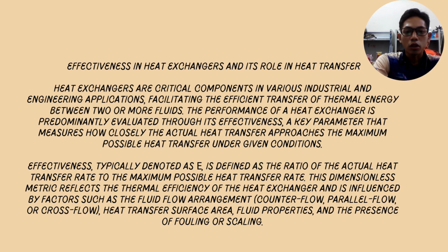Effectiveness, typically denoted as E, is defined as the ratio of actual heat transfer rate to the maximum possible heat transfer rate. This dimensionless metric reflects the thermal efficiency of a heat exchanger and is influenced by factors such as the fluid flow arrangement, counterflow, parallel flow or cross flow, heat transfer surface area, fluid properties, and the presence of fouling or scaling.